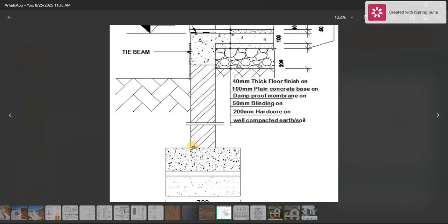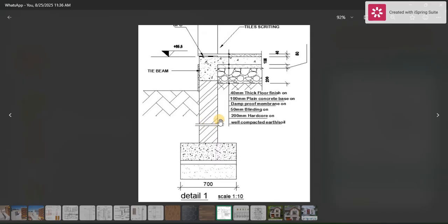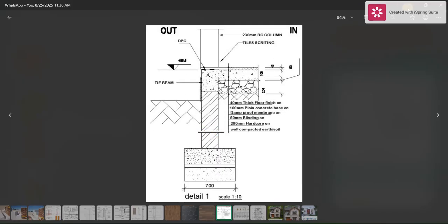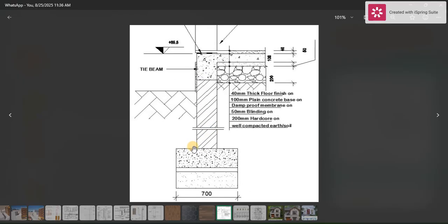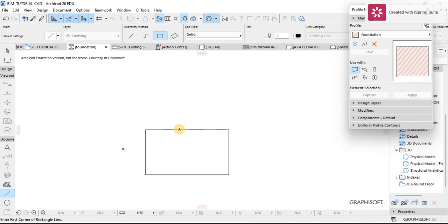Yeah, with that done, now we have a footing, and the next thing we're going to be doing is putting the concrete or the masonry wall. It is for the strip foundation. So that's usually a meter high. I'm going to draw it at the middle of where everything is, and I'm going to make sure it's a bit thicker, like 250 millimeters thick, and then the height is going to be 1,000 millimeters.